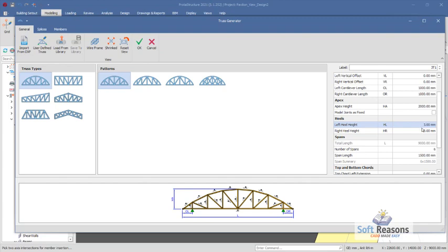So fascia board is always between 250 to 300 millimeters. So you can do that. Key in 300 millimeters. You can see the changes on the truss right there. So the truss span is going to be like 10. Okay, so we have it to be 10 right there.